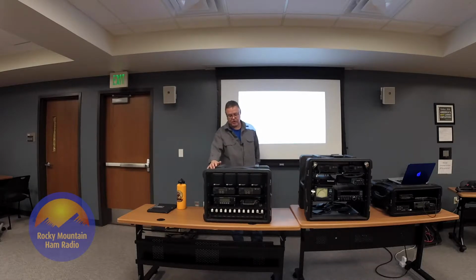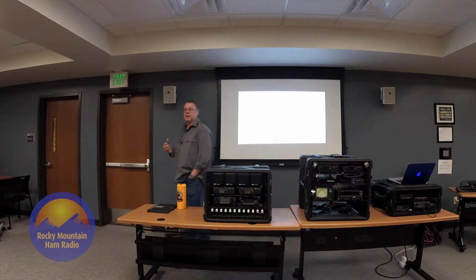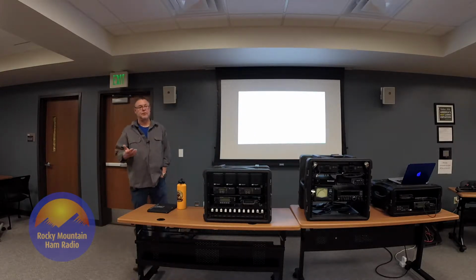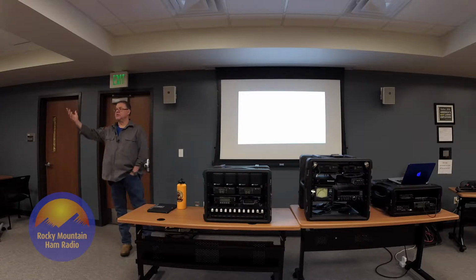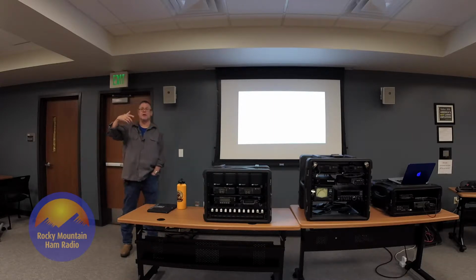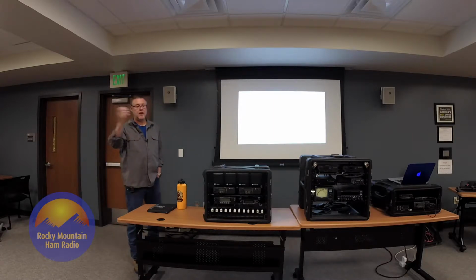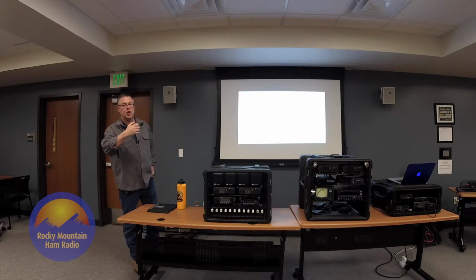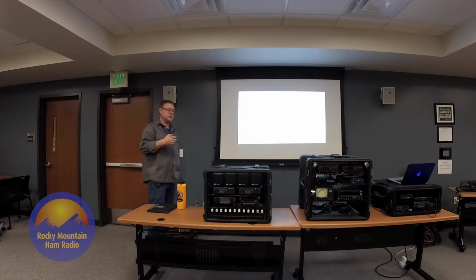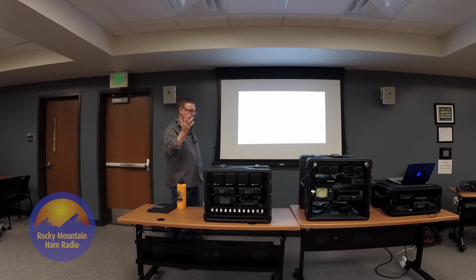Mine, I was getting all fancy when I built it. And this one in the beginning had a power switching, basically an automatic transfer switch, if you know what that is. If a building such as this has a generator on the outside, the transfer switch transfers power when mains are lost over to the backup generator system or solar system or whatever it may be.